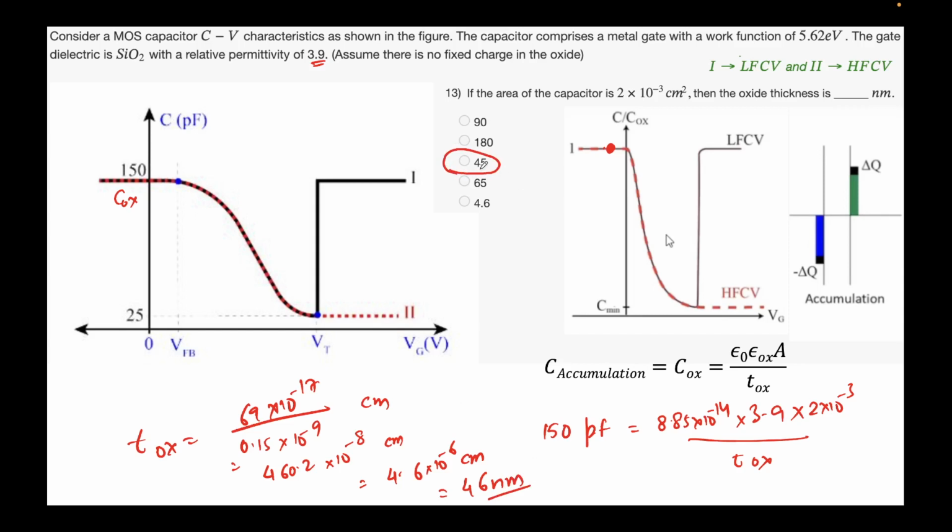As I've been saying, if you know the formula, anyone can solve this. What is the understanding that we have here? The key takeaway from this problem is, first of all, the range of values that you see. Typically the capacitance values are in picofarads, and today the practical values are even in femtofarads. One of the other key things to take note of is the oxide thickness.